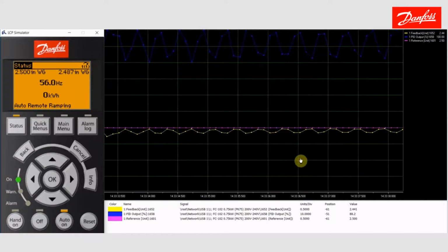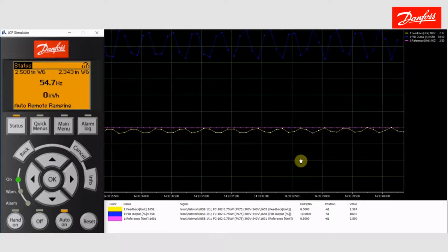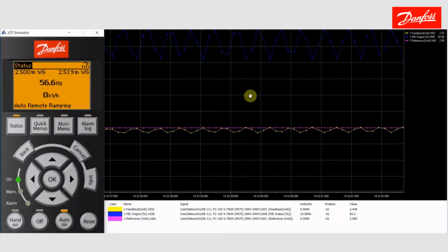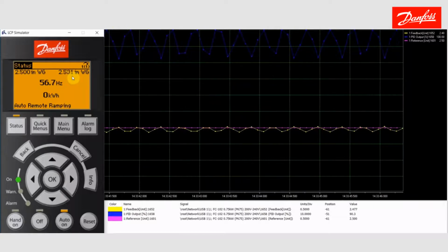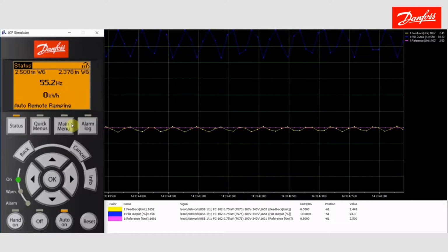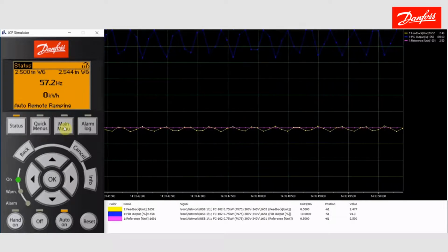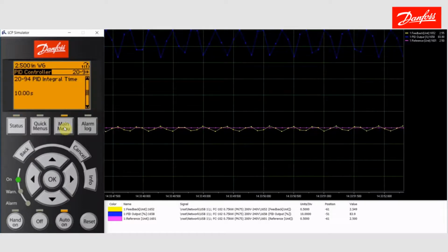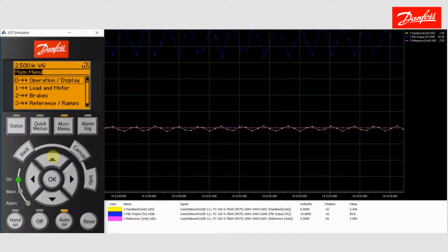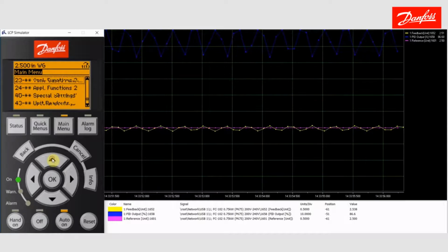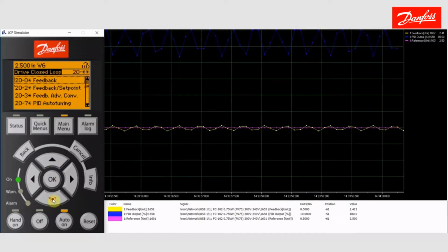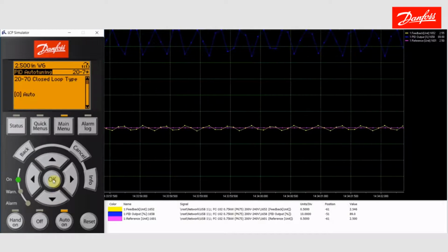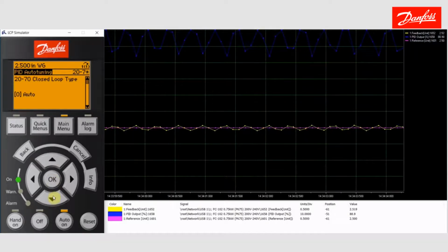And it was actually pretty rapid, but again, we're not stabilizing. We're over and under the set point, as we can see over here. So what we'll do now is execute the auto tuning. So I want to do that now. I'm going to do that group 20. And we will see what type of numbers that the system comes up with.